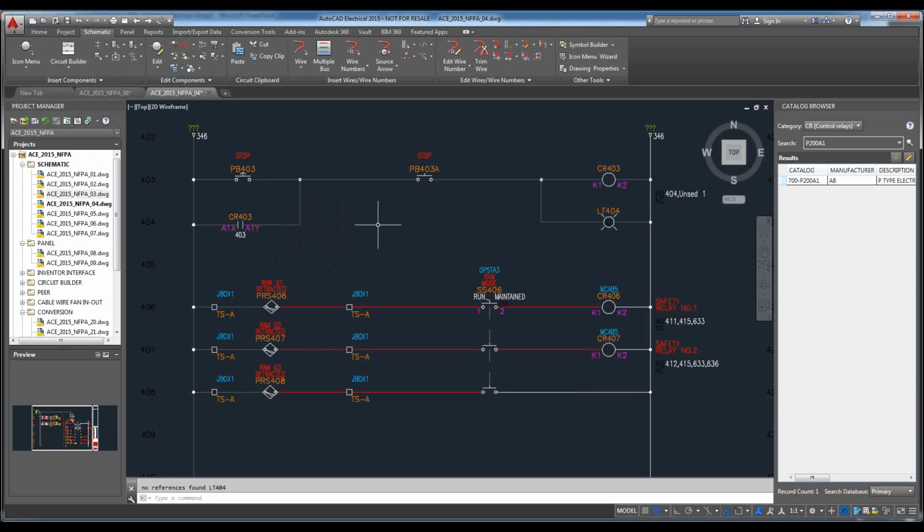So creating lines, not lines anymore, actual physical wires with actual gauge types and intelligent information. Placing those components, and automatically breaking those lines and creating those connection points, and automatically referencing component tag information. Changing up drawings, information is going to change, as well as cross-part referencing. So I knew that I only had two normally open pins available. I could not use a normally closed contact with that master coil.